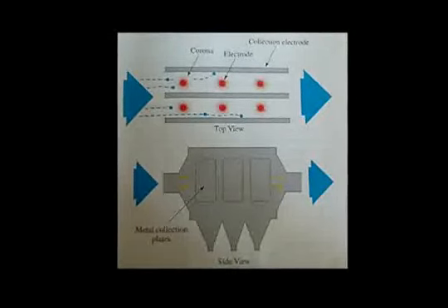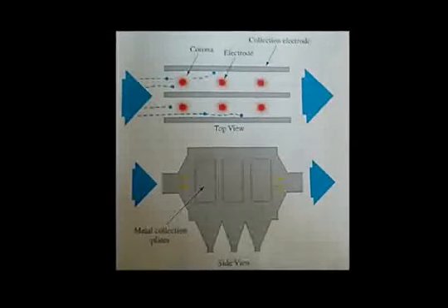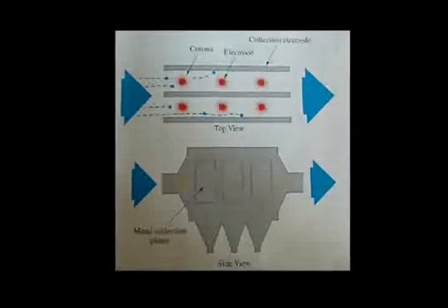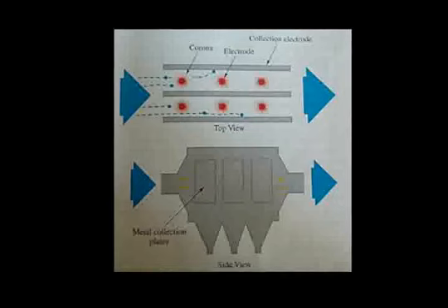A grid of electrodes is installed into the stream of pollutants. The electrodes are charged between 45,000 and 75,000 volts, forming an ionized field or a corona around each electrode. A corona is an area of ion or static charge surrounding a high voltage conductor.